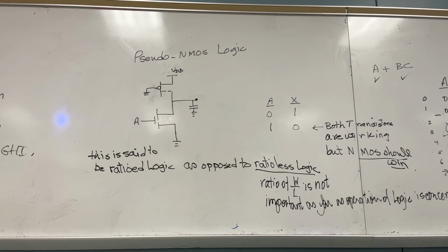And also, the major thing is the power, static power. We are not talking about dynamic power. We are talking about static power, which means the inverter is not switching. You don't understand what dynamic power and static power mean? Static power means the inverter is not switching, it's at a stable state. Did you get it? Dynamic is when it is switching from 0 to 1, 1 to 0.